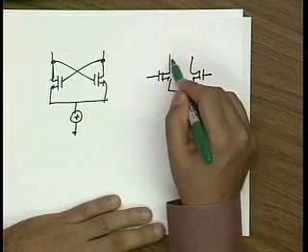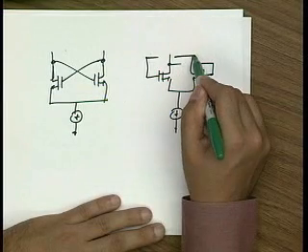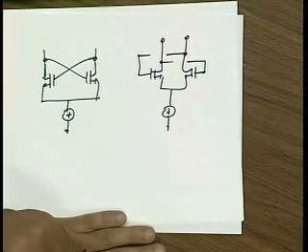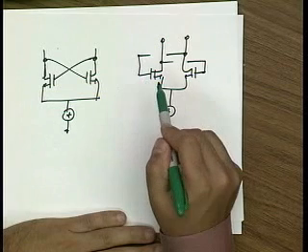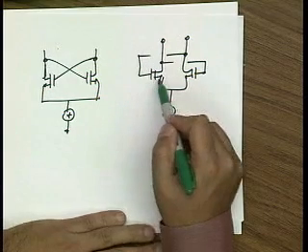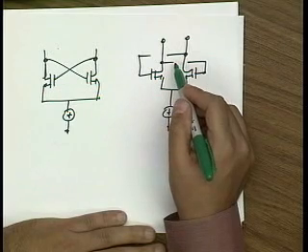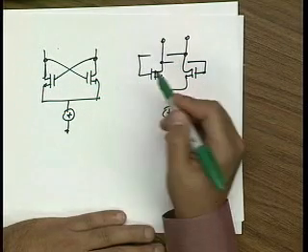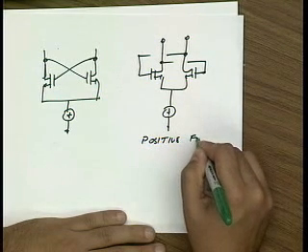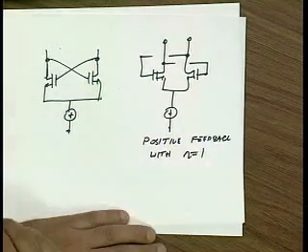Where I've taken this output and connected it here, and taken this input and connected it to this output. So from a feedback perspective, the gain from here to here is positive, right? And so bringing this back is actually positive feedback. And the n factor is in fact 1, right? I'm just taking the output and connecting it back into the input. So this looks like positive feedback with n equals 1.